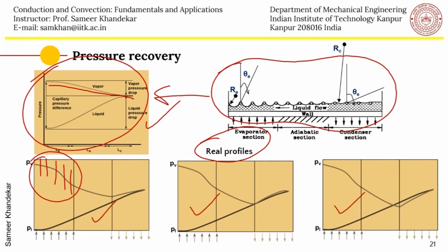So coming to the end of the lecture, we have seen how to evaluate the performance of a heat pipe. We have derived the capillary limit of a conventional heat pipe. The other limitations we have not touched, but we have understood them, and we have learned to plot the performance curves of a wicked conventional heat pipe. So with this, we come to an end of this lecture.